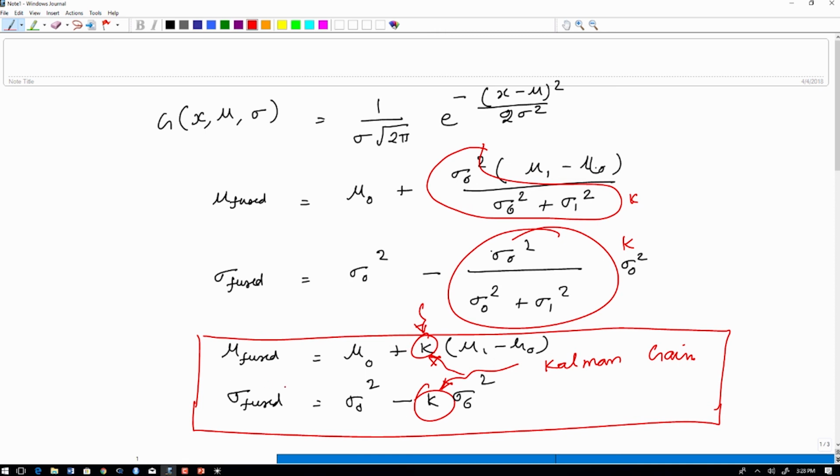The only thing is that here we need to add the variance also into the picture, because the Kalman filter is based on the probability distribution, in order to handle the uncertainty. This is for the 1D case that we have seen. If there are many parameters involved, more than one measured variable, let's say not only x but also velocity, the calculation becomes much more difficult.